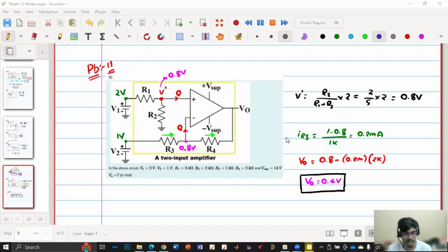There are again two things. One thing is in the datasheet, every time they say you operate as an amplifier, they'll provide some resistance value that it should be within a few kilo ohm range, else the op amp will get loaded and it will not work like an amplifier, not exactly like an ideal op amp.